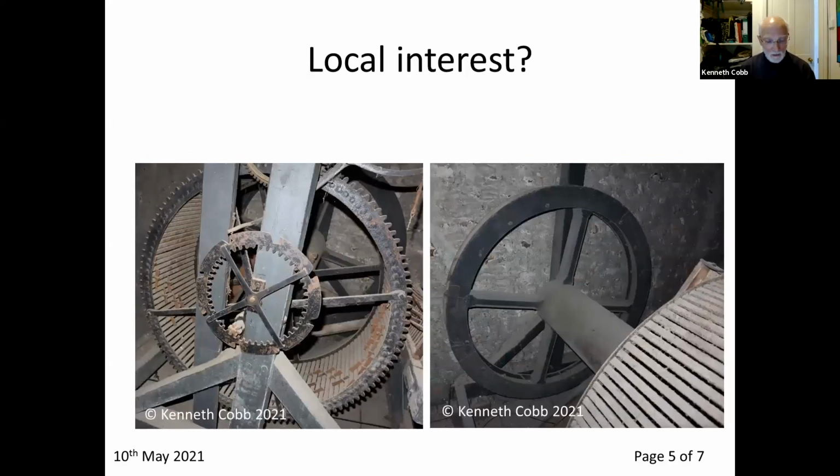Progression of the tune barrel, on the left-hand side, is controlled by an 8-notch count wheel, seen here in the center of the left-hand image. A count wheel stop arm is seen towards the 11 o'clock position of the count wheel. This would have been momentarily lifted by a mechanical tie controlled by the tower clock. The apparatus would have rotated until the count wheel arm dropped into the next notch.